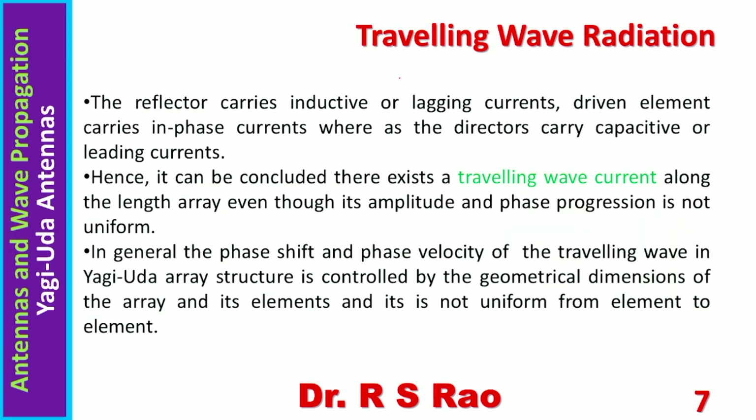Some more points regarding Yagi. The reflector carries inductive or lagging currents, the driven element carries in-phase currents, whereas directors carry capacitive or leading currents.